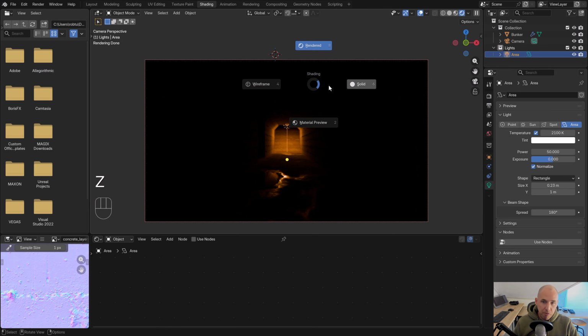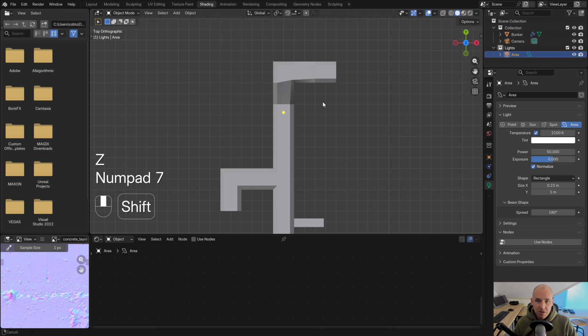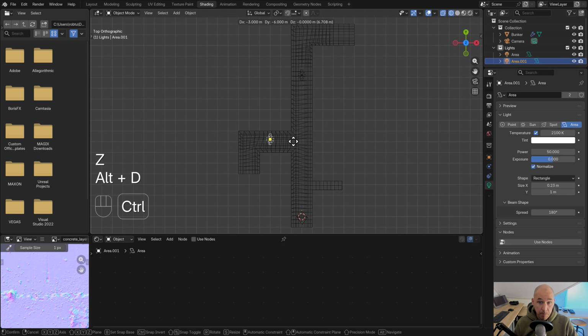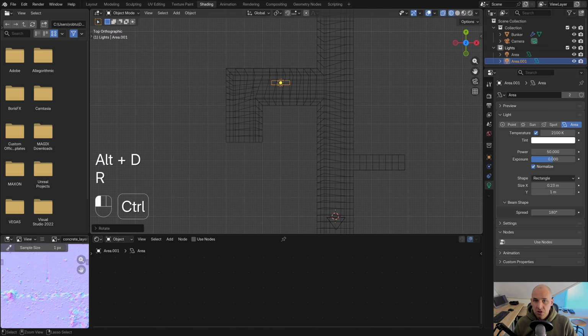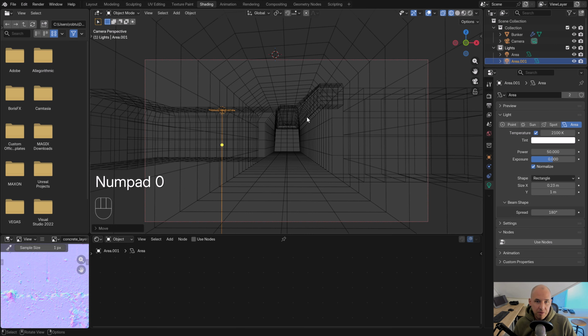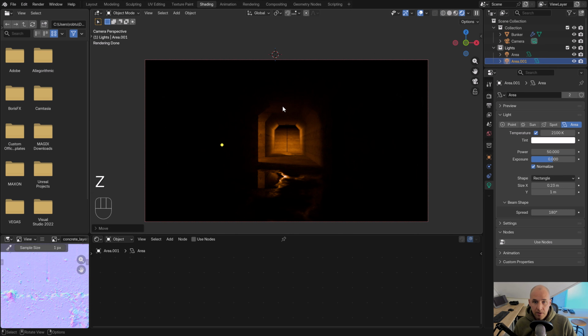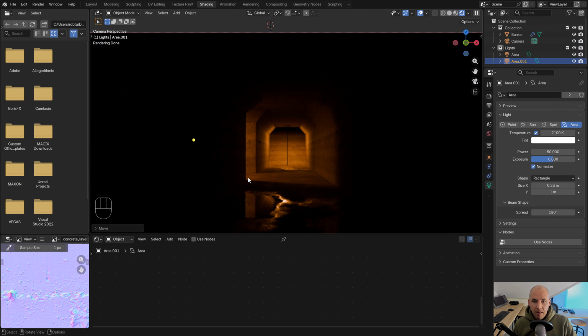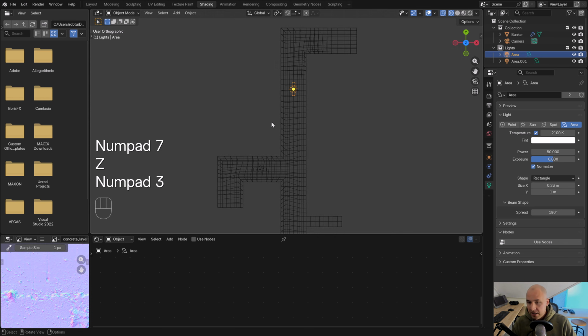We just have one lamp for now, so we press Alt D. As soon as we change values, it works both ways. So if we change the value on this light, it will automatically change on the other. If you do Shift D, then you have a unique light. The reason I like this is that you have a light here, then a little bit of darkness, and then the light over there. So I prefer to have this light as far as we can.